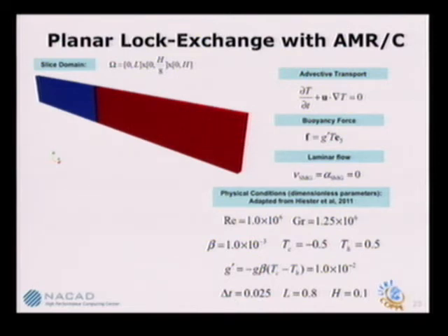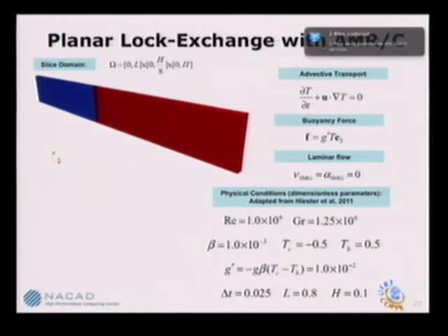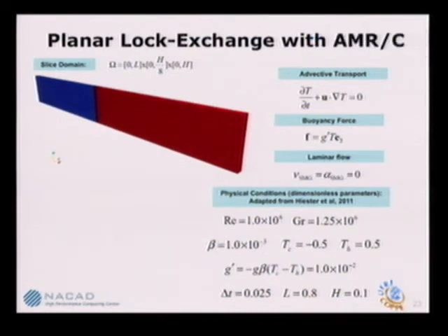The temperature is responsible for the buoyancy, and the coupling is temperature. We have advective transport of temperature, and buoyancy dependent on temperature. We just drop the Smagorinsky model under the idea that the flow is not particularly turbulent, so we don't need to add this additional viscosity. The mesh resolution will try to do the trick.